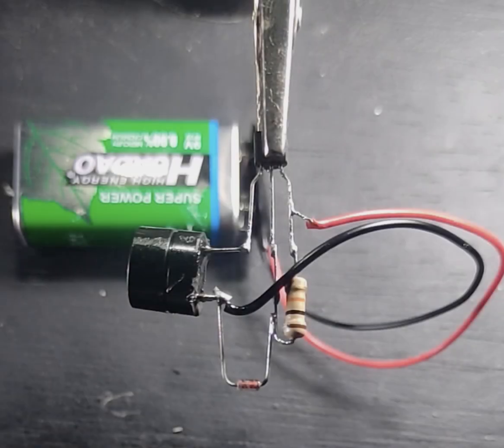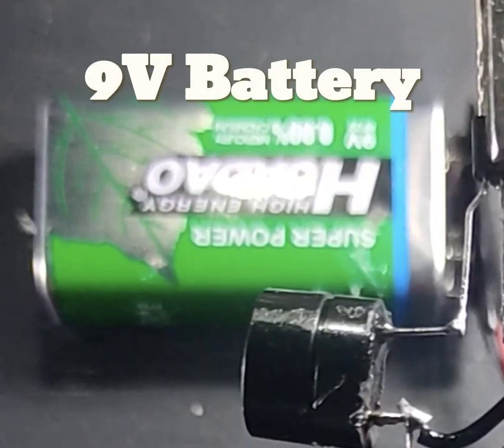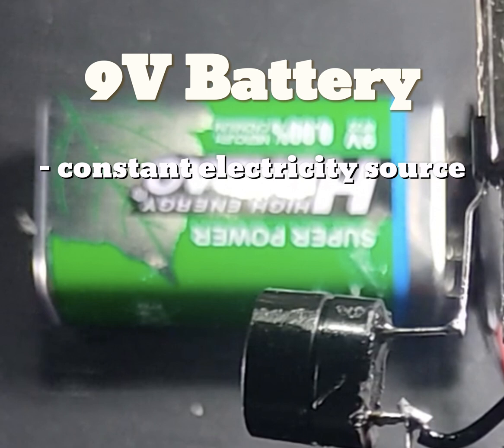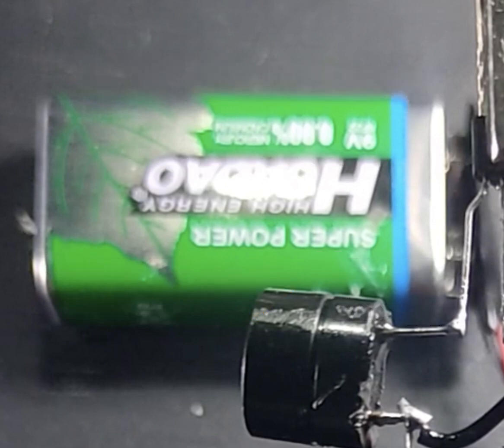So after we now understand the basic facts of electricity in the heat sensor circuit, let's talk about the components of that circuit, such as the 9-volt battery, the transistor BC547, the buzzer, the resistor, and the diode. The 9V battery provides constant electricity by converting chemical to electrical energy, which is then pushed through the circuit using the imbalance of electrons on the positive and negative terminals.